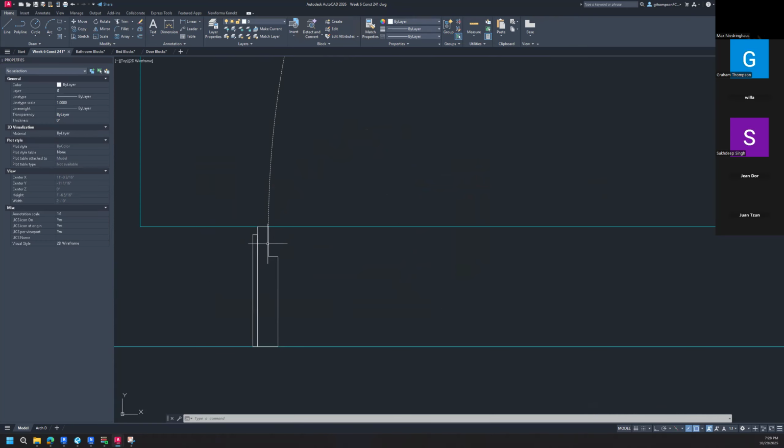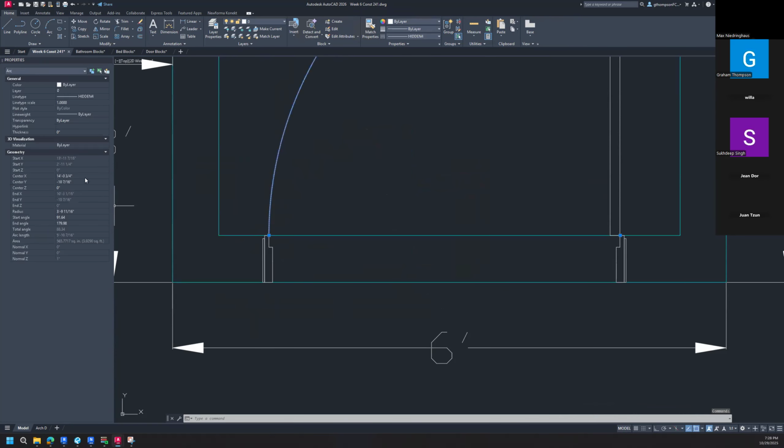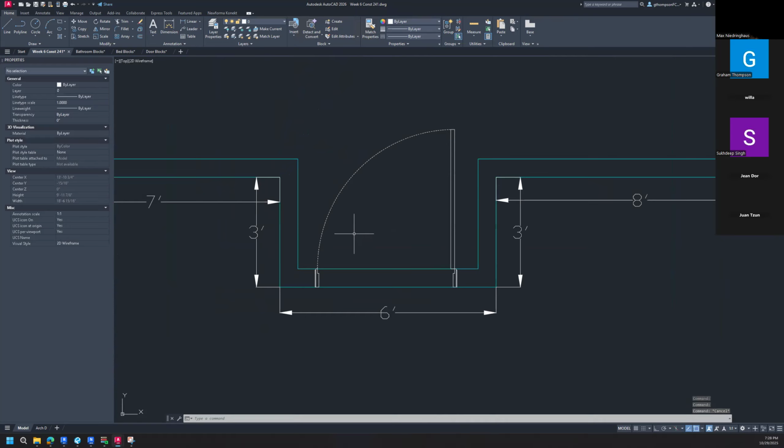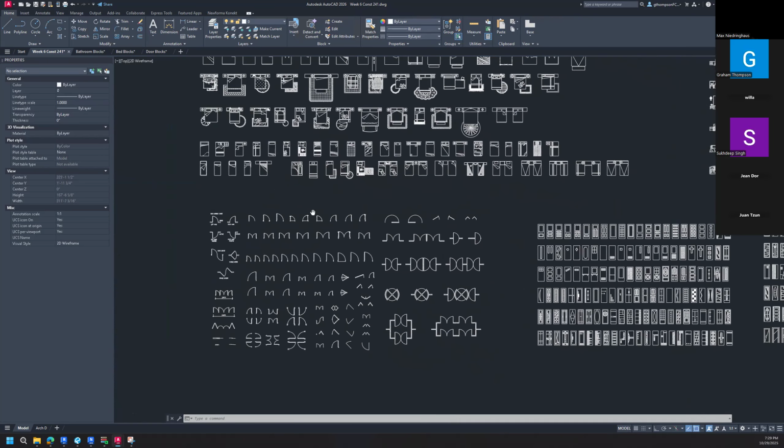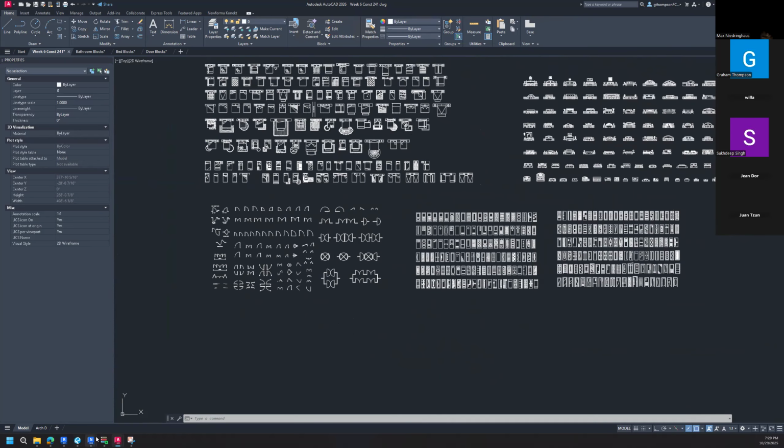So depending on that, these were all different polylines, and you can see the line type and the line weight and what layer it is, and maybe you didn't want it hidden. We could change it to a different, dashed layer, right? So you can do anything you want to these blocks. They're just a starting point. So don't be like, hey, I don't have a block that does this. We can take whatever you have and update it, modify it, use our commands that we've learned. Like, Will drew all those blocks from scratch. We now, if we go over to the kitchen blocks, which we're going to bring in right now, nice segue, Graham.